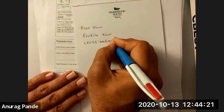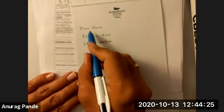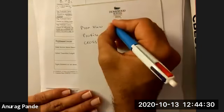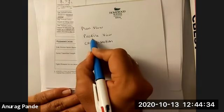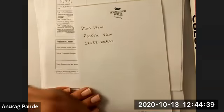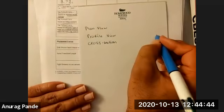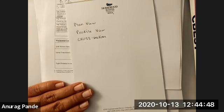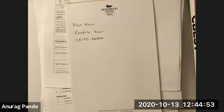When you talk about the plan view, that's your horizontal curve criteria, basically a bird's eye view. You look at things from the top. In the profile view, that's very important for the vertical curve design. That's what we talk about when the drivers are trying to navigate that profile view going up or down, things like that. And the cross-section is when you're trying to navigate the roadway, how are the lanes situated?